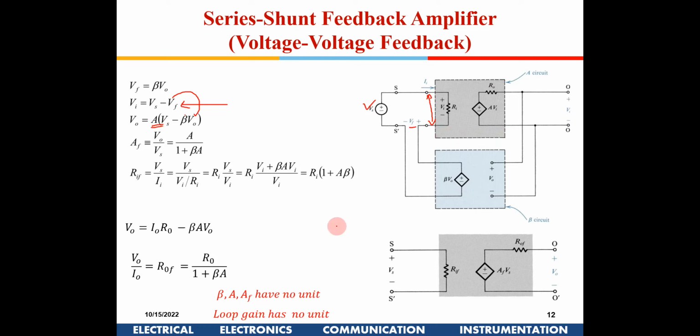Understood, sir. Yes. Yeah, tell me. The circuit which is drawn below, is that the equivalent circuit for the upper circuit? No. The bottom circuit is drawn to compute the output resistance, in which I am giving an output voltage. If I give an output voltage out here and Vs is equal to 0, then this is how the circuit will look like.